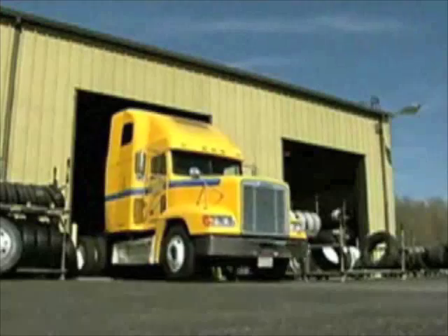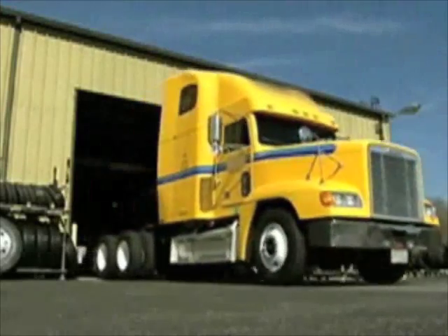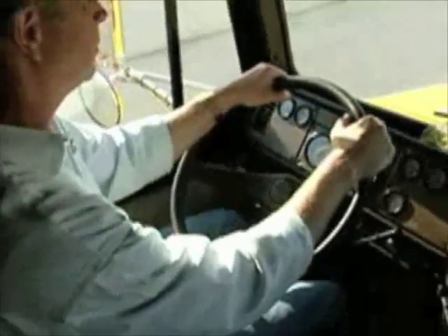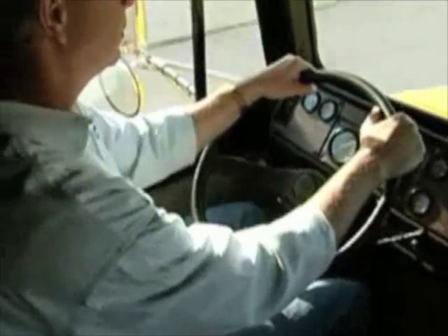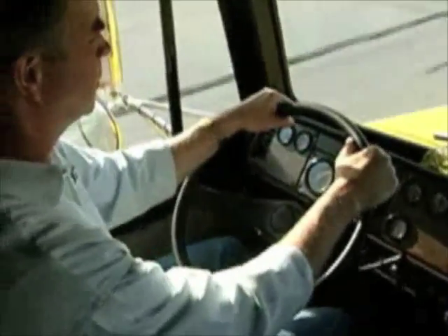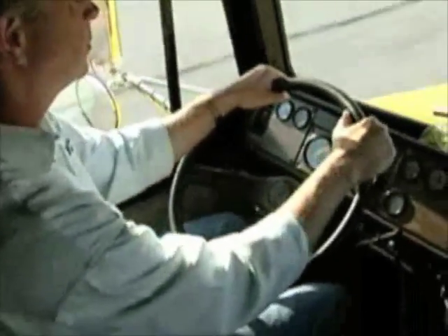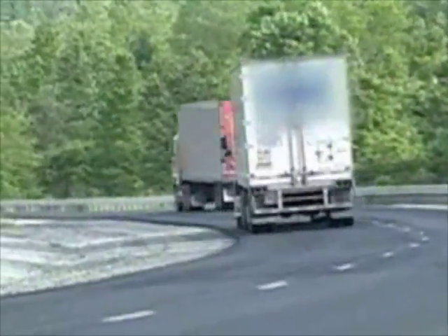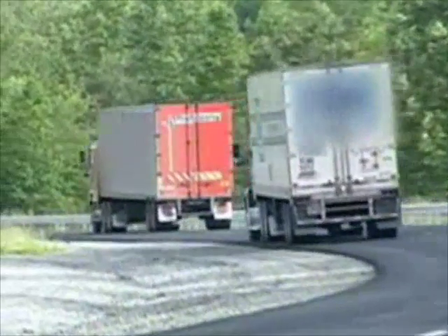Prior to doing the actual runout measurements, take the vehicle for a road test. This will enable you to experience the vibration firsthand and check the range of speeds at which the vibration occurs, the frequency of the vibration, and the primary position where the vibration is coming from. You should run a minimum of 5 miles to allow the tires to warm and reach operating temperature.